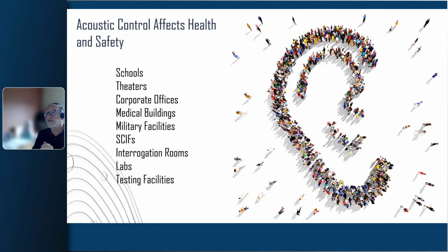But even at STC 50, we're seeing a broad number of manufacturers that can achieve that rating. And that's similar to what you might see in an 8 inch thick wall, an 8 inch drywall partition. So the trick is to be able to achieve that kind of acoustic rating in a 1 3/4 inch operable door panel.